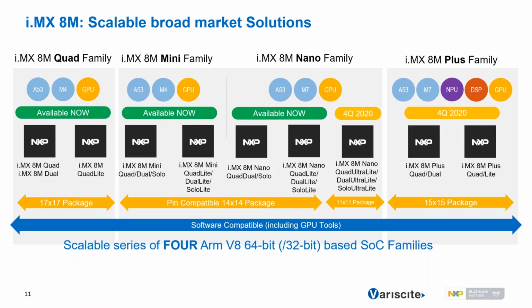family. The 8M Mini and Nano, launched in 2018 and 2019 respectively, transitioned to the 14 nanometer FinFET process node, significantly reducing the power profile while adding key features such as video encode and support for digital microphones.